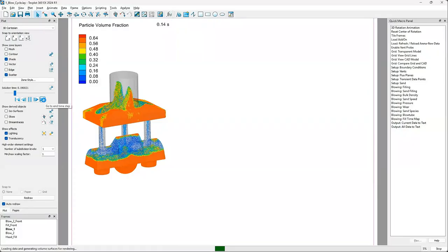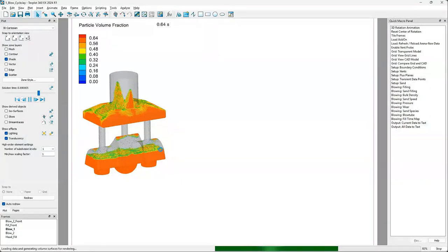So what we're looking at here is, the tubes run empty. There's really not enough. There might be, but the way it's distributed in the magazine, there's really not sand enough to fill this core. Right? So the solution would be to do a double blow. Okay, so replenish the magazine and blow again.